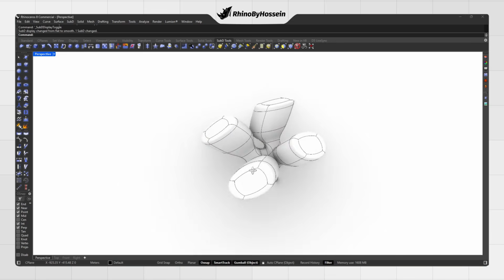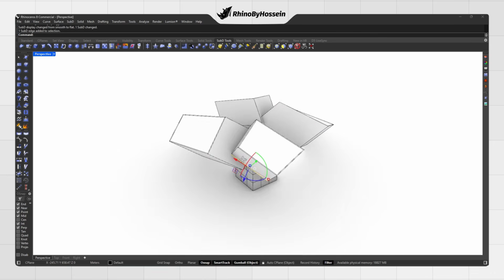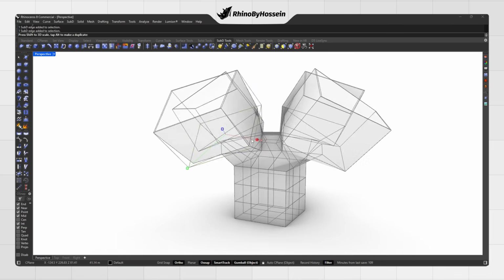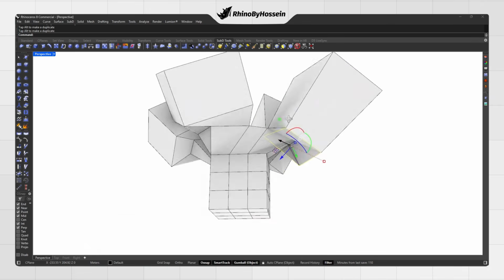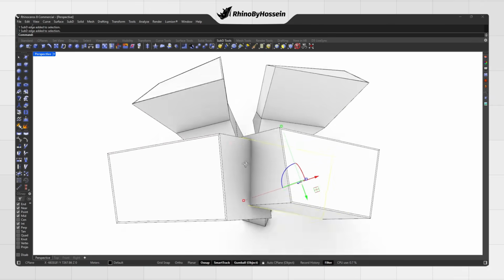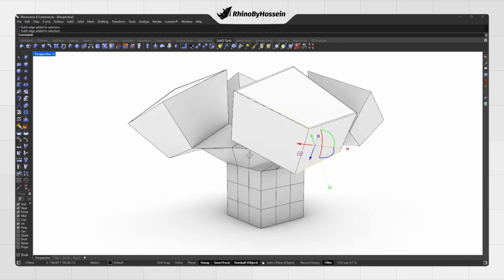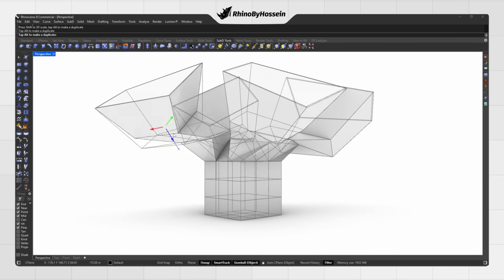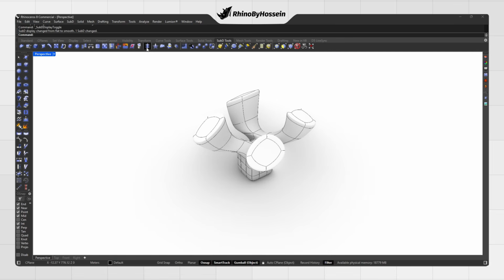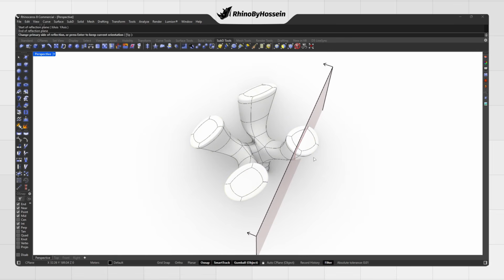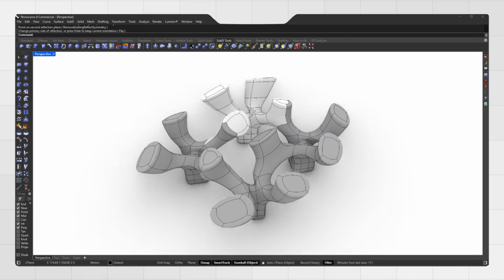One of the biggest advantages of SubD in Rhino is that, when needed, we can convert a SubD model into NURBS surfaces. This allows us to take advantage of the precision of NURBS for further design work, manufacturing, or preparing files for production. That is why Rhino today gives us both the accuracy of NURBS modeling and the flexibility and speed of SubD modeling. Of course, this does not mean that SubD has replaced NURBS. Each method was designed for a specific type of modeling, and once you understand both workflows, you can choose the best approach depending on the needs of your project.